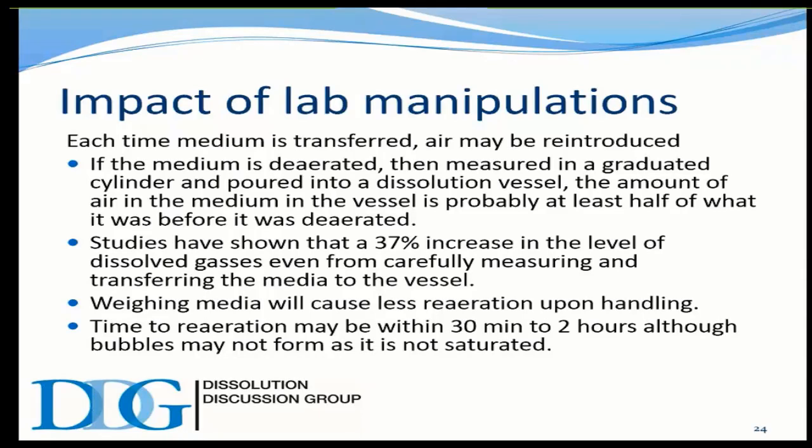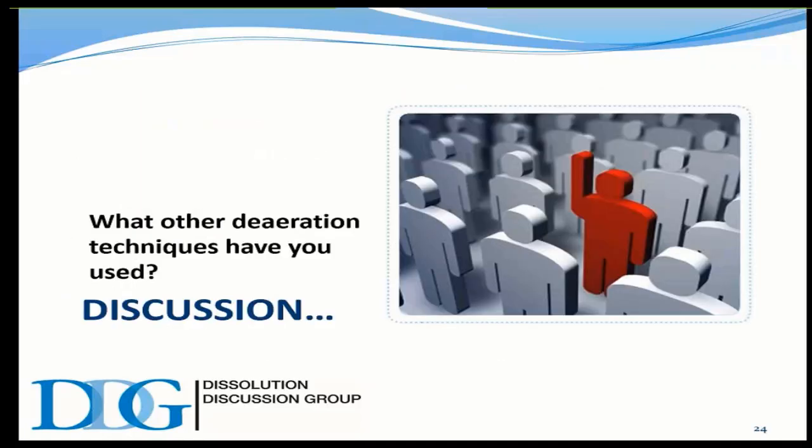Also, time to reaeration is typically anywhere from 30 minutes up to 2 hours, and out to about 5.5 it seems to reach equilibrium. But just remember that even though some air is partitioning back in, it doesn't mean it's going to form bubbles. Bubbles form because something is saturated and it's now coming out, or it's supersaturated, and these bubbles are now forming. So anyway, hopefully that sets the tone for any discussion.